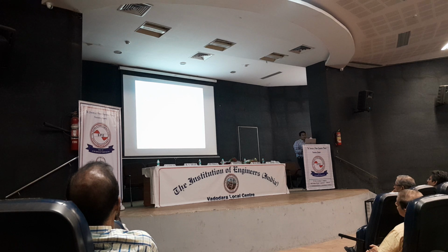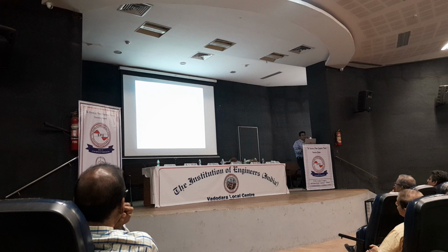When you look here, the first value is 54.82 megawatt. That is the active power flowing from bus number 2 to bus number 5. Reactive power is around 7.34 megawatt ampere reactive. Whatever you are transmitting and whatever you are receiving, there might be some difference, because there will be line losses.